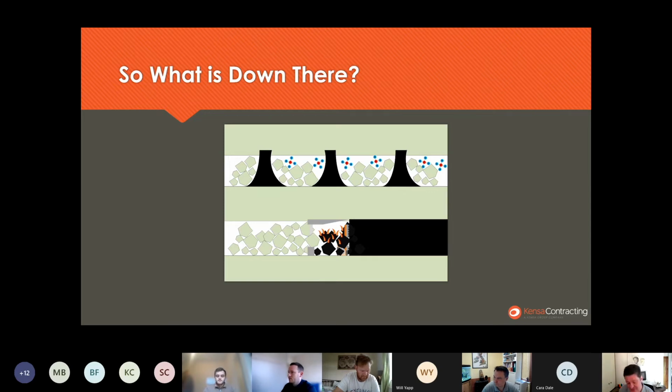Any other questions? How does the loop pass through the void? It just goes through, it just hangs through the void. It can be a tricky process. It can mean that the loop gets stuck, but a lot of times because they put weights on the bottom of these things, they hang true and they'll just go down to the bottom. If you're casing it, obviously, if you're putting a sleeve on the outside, then it just goes down the sleeve like any other installation. The drillers are very skilled at this because a lot of social housing, particularly, is in previously mined areas because of the social circumstances of the areas, and therefore the drillers have got very good at dealing with mines.